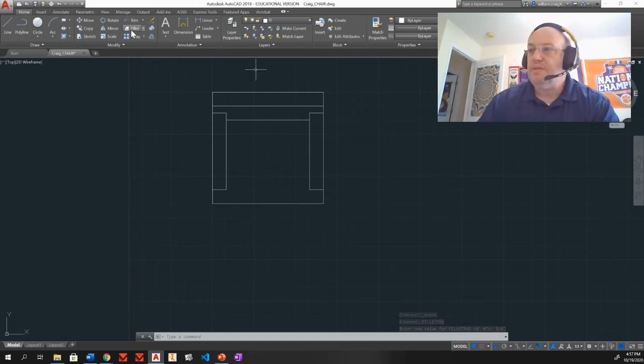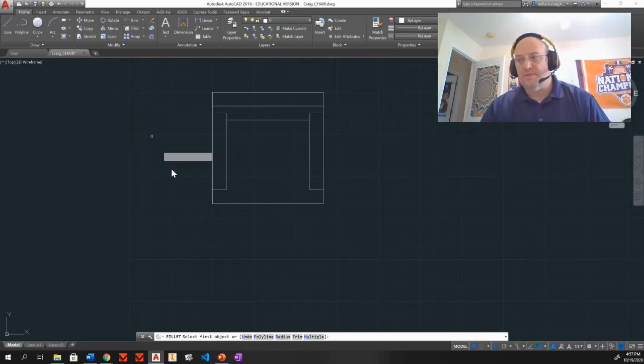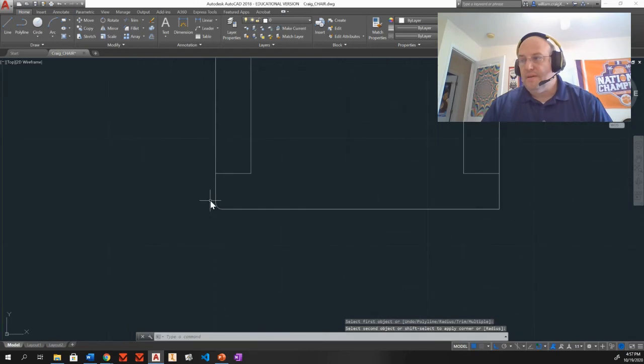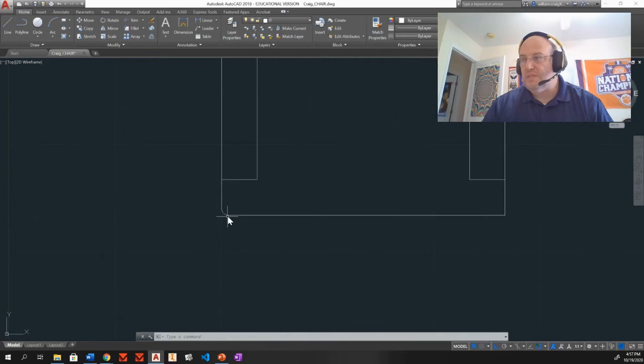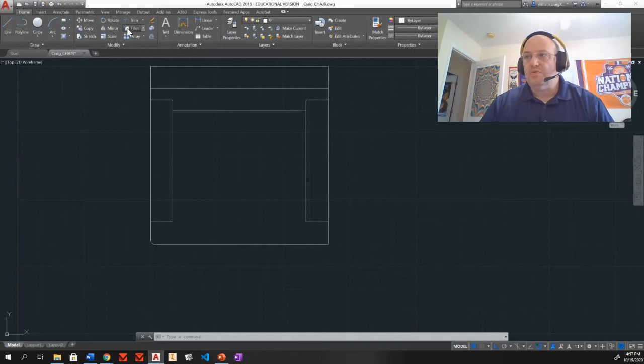Now we're going to start doing the fillet. And it tells us right here in our 6C to do the front corners of the cushion first. There's a reason for this. It has to do with what goes away. So I'm going to grab the left side there. I'll grab the front. And you can see there's that nice little 3/4 inch radius fillet. It's nice and rounded off for us. Smooth this over. Grab the tool. I still have that radius set, so I'm going to go here and here. Very good. The front of my cushions are done.